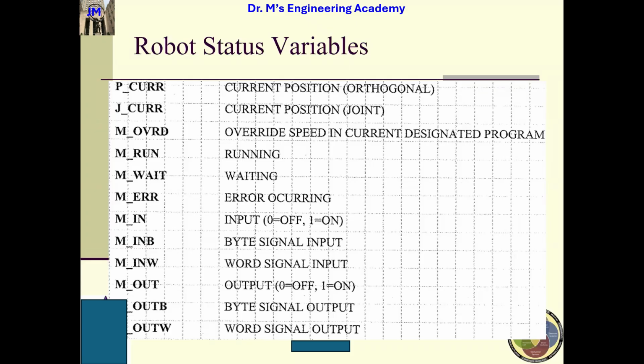So usually, after we finish a new program and we have not tested how it works, we use a very low speed. Okay, I want you guys to write down. Whenever there is a new program, especially if this program is very long, very complex, when you test your program, you always need to lower the speed to 10% and make sure everything is in order.